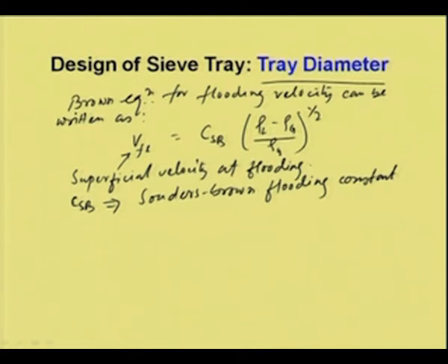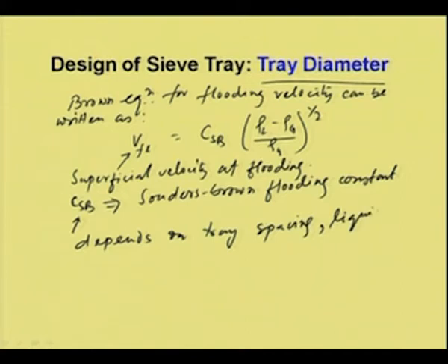In general, this is not a constant, it depends on tray spacing, liquid load, hole area on a tray, and hole diameter.